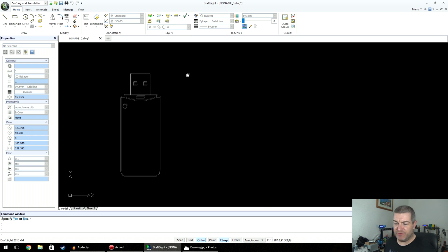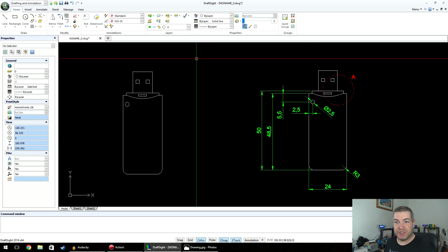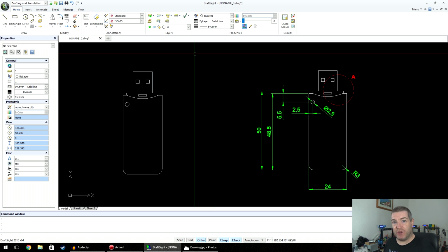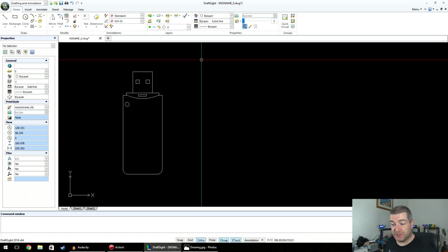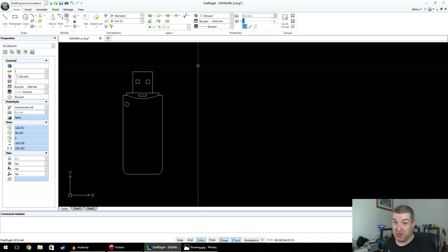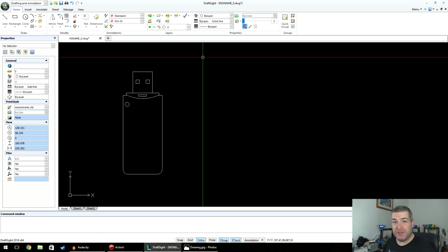What I'll do is, if I move that to there, I'll try and superimpose the original drawing next to it, so you can see what we've created using lines and circles, and in this case 3-point arcs. We've also used offset. We've used stretch by using the control points. We've used trim a lot. Trim and offset you use a lot. And we've used fillet. So once you can create that, that's it. Your 2D CAD skills are done for what we need to do here.